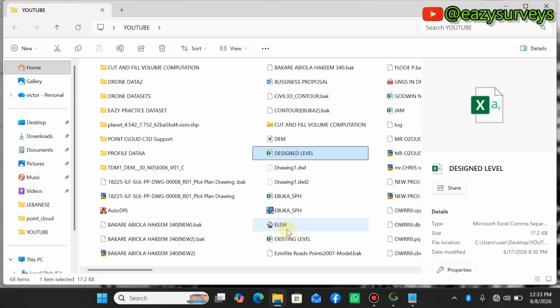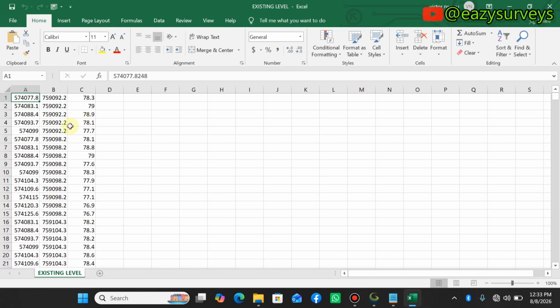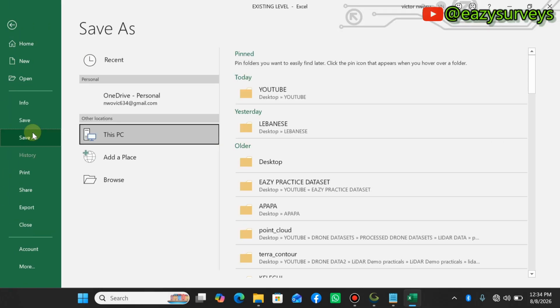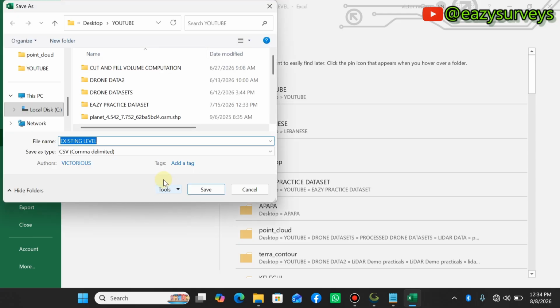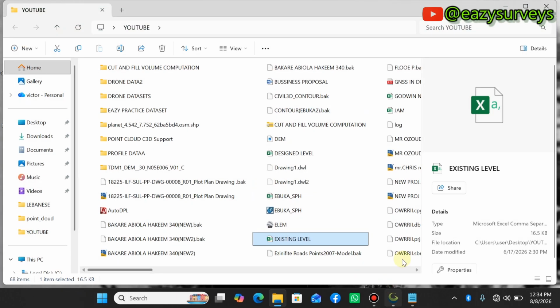So these two sets of data must be tabulated in Excel. You must have it tabulated in comma delimited. So you can see here is distance, here is northeast, and here is the elevation without the heading, and it must be saved as comma delimited in the folder. So here is the right extension. After you have your data prepared, you need to close your Excel worksheet.